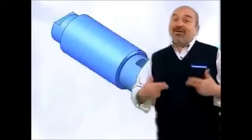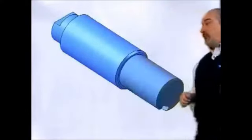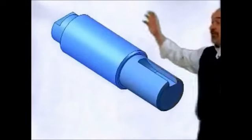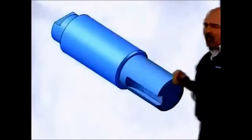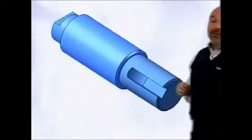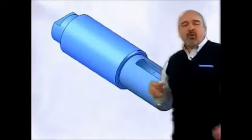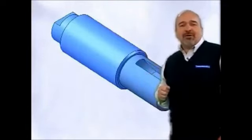Simultaneous requirements, again, because I keep getting questions about this. Let's say we have a shaft with a key seat on one end and a pair of flats on the other. The question is, how well do they have to be oriented to each other? On the drawing, they're shown at 90 degrees, so we know what the goal is. But what's controlling their perpendicularity to one another?